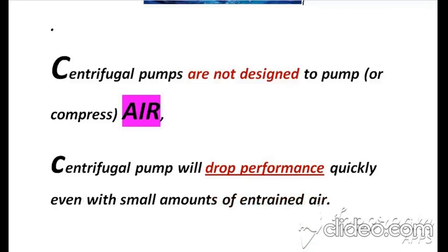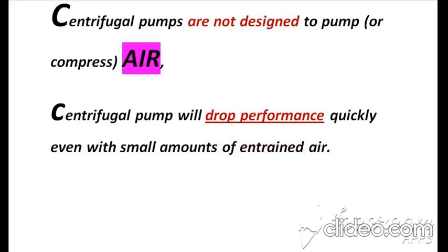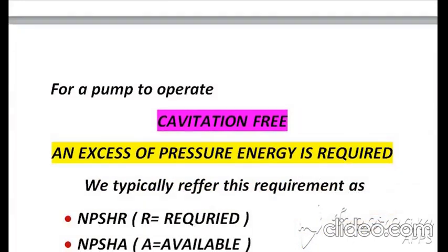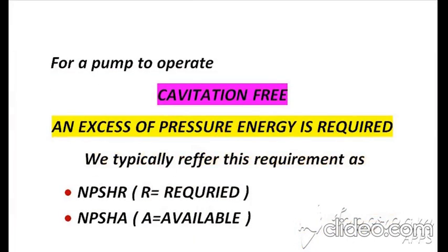A centrifugal pump will drop performance quickly even with a small amount of entrained air. So for a pump to operate cavitation free, an excess of pressure energy is required. We typically refer to this requirement as net positive suction head required and net positive suction head available.